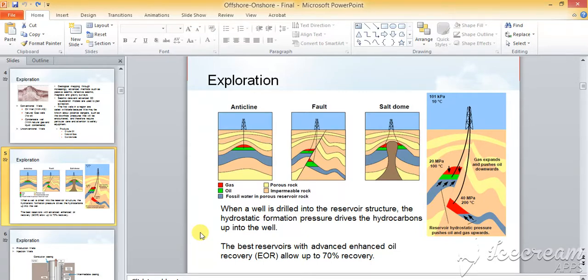The best reservoirs that we consider initially operate with their natural lift, and later on, to have an enhanced oil recovery, we use a couple of other methods. The first method that we use for enhanced oil recovery is when we see that the reservoir pressure is depleting, we start injecting water inside the reservoir. Due to the density difference, the water will settle down underneath in the reservoir, so it will start uplifting the oil in the upward direction.